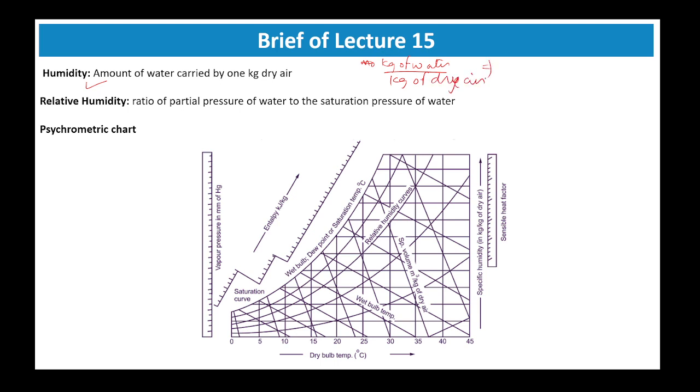So it can be calculated by, since for the vapor or gaseous phase it is easier to calculate in pressure, and pressure is also a kind of concentration. PA is the partial pressure of water at the temperature. So humidity is PA divided by what will be for dry air, which is the total pressure minus the partial pressure of A. So this is in terms of pressure.